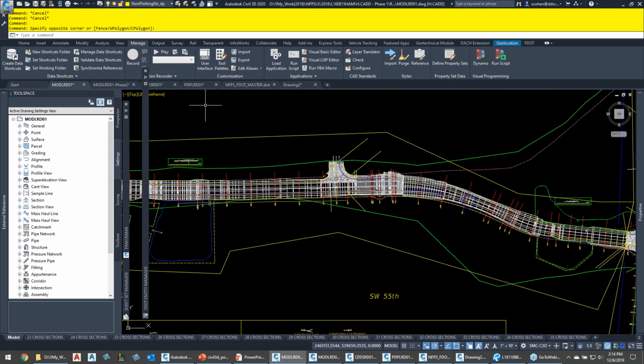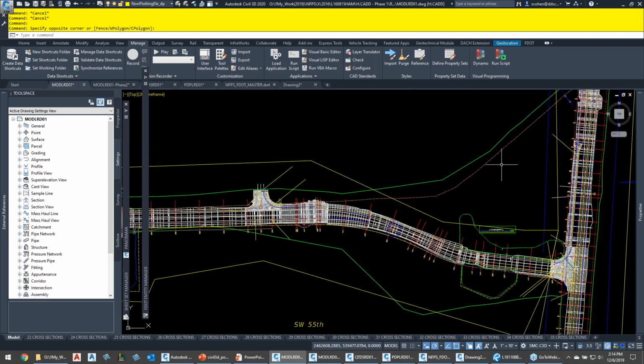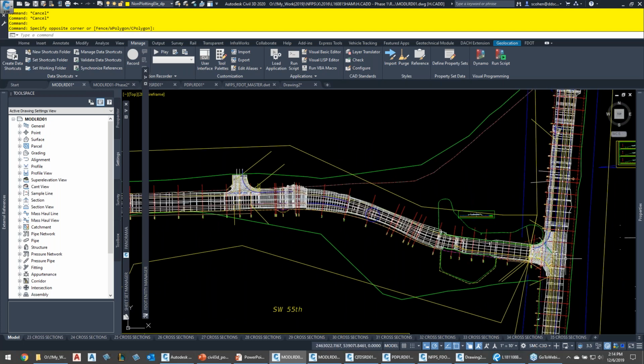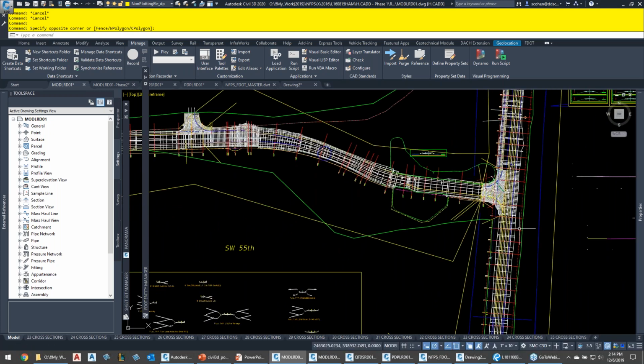And basically, there's a school complex up here, and we have to widen the road. And the original road actually comes this way. We're basically going through here. This is a DOT road, so we have to widen the road, put an additional lane, and we were going to mill the road, of course, to redo the striping, right? So we just mill paved 2 inches, and we have 2 or 3 inches, and we basically have to put down a shoulder and widen the shoulder and upgrade the shoulder because the shoulder, of course, is now pavement and widened.